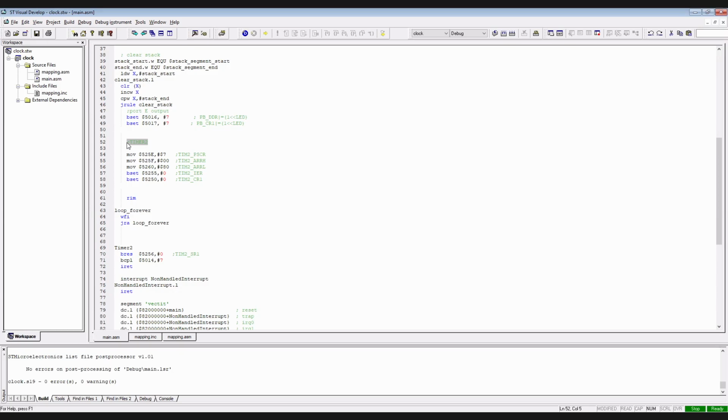Essentially, the timers are the counters, and timer 2 can be used in its most basic way to count upwards from 0 until a specific value which we set has been reached. It is then reset back to 0 and starts again, triggering an interrupt at that time.